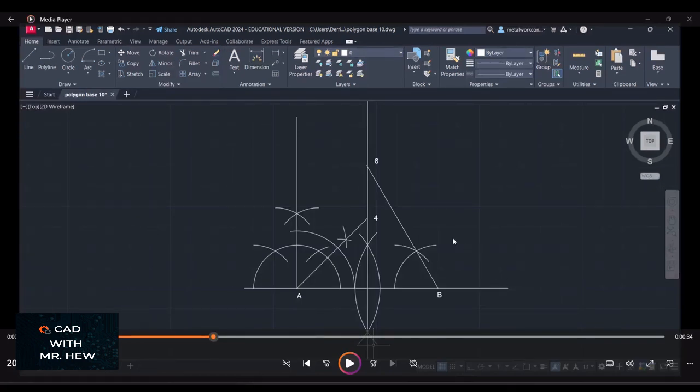So here is the bisector where my mouse is, and what it is doing is dividing the line AB into two equal parts. So what you do, you put the compass at A, radius is any radius as long as it is greater than half the length of the line, and then after you scribe this arc, you put the compass point at B, same radius, and mark an arc. Where the two arcs intersect, you draw a line, and that line is called a bisector.